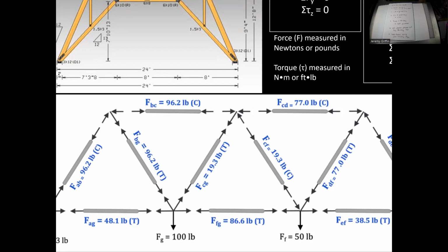So first of all, you want to know compression or tension, because there are certain materials that you can build with, right? And they have different compressive or tensile strengths. Concrete, for example, has almost no tensile strength. It's really good at compression, but it's terrible at tension. You pull on concrete and it'll just pop apart. So you would not want any structure with concrete under tension, because that wouldn't make any sense, right? And then, okay, so let's say you're building this out of steel.